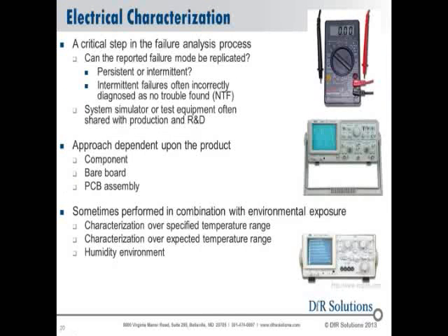Electrical characterization is pretty much another essential step. You always want to try and power the device up or read voltages, currents, resistances, wherever possible in order to confirm that the part is actually failing in the condition that it was reported to be in.